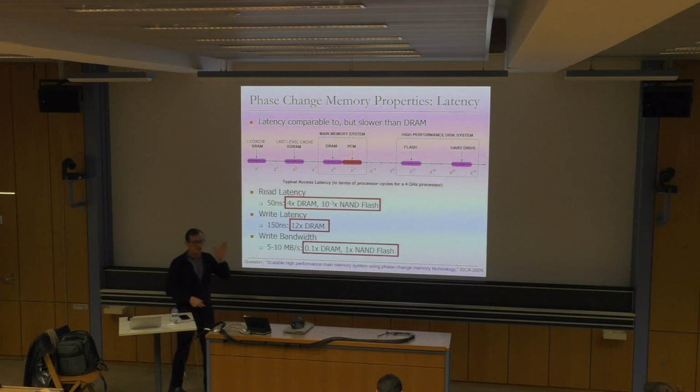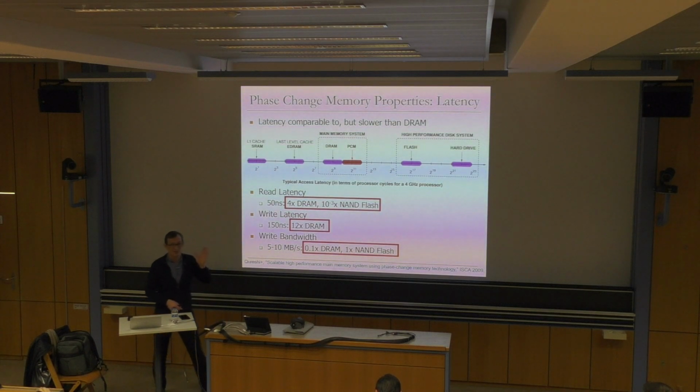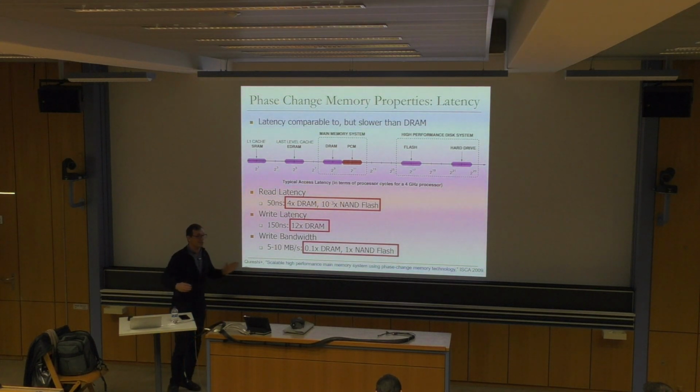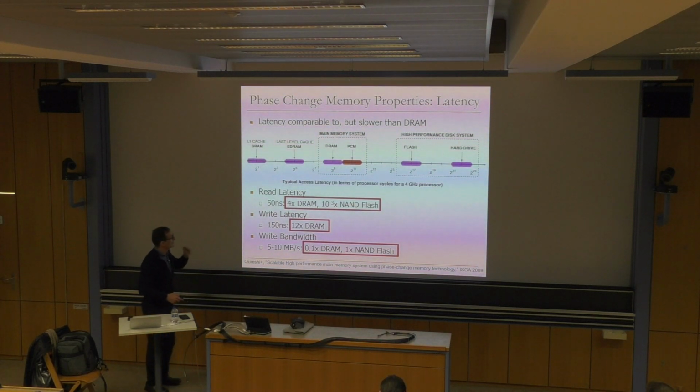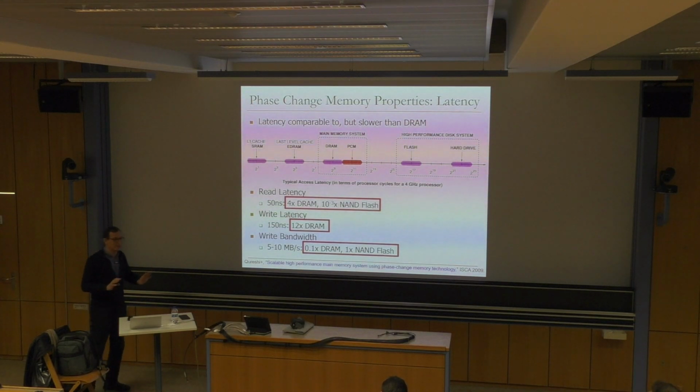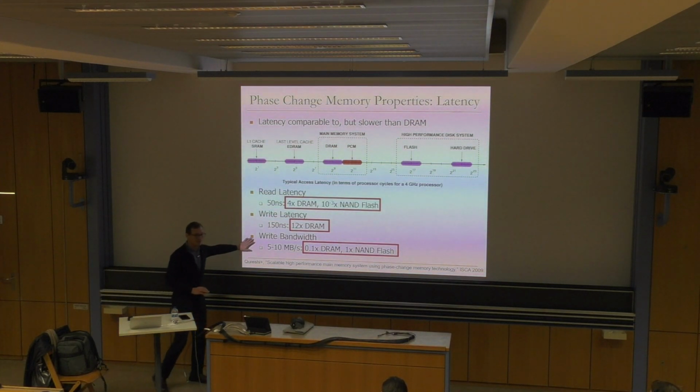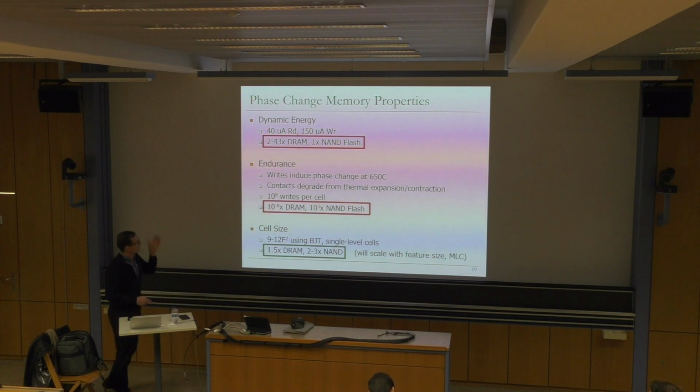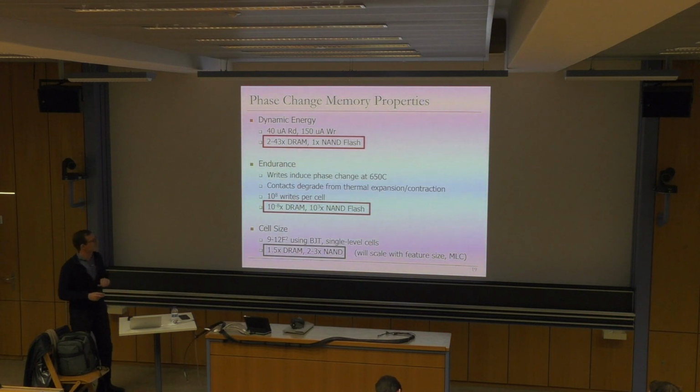And those high temperatures are hundreds of degrees, which is not good. Which means that you cannot sustain a lot of writes at the same time. That's why your write bandwidth is not as good as DRAM here. Of course, people have developed the technology a lot over time, and it's become better. I believe 3D XPoint does a better job than what was reported 10 years ago. But they don't expose a lot about the system, so we don't know.